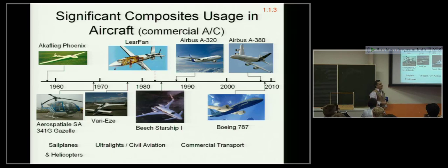In the 70s, he recognized that these composite materials would give certain advantages. They could give you pure laminar flow, because if you make the whole structure without any rivets, and you can maintain the aerodynamic shapes you want, which you can with composites with the use of proper molds, you can actually get laminar flow, and your drag goes way down. And he also recognized that you can generate shapes, such as canard shapes and so on, that will give you some extra performance in certain windows of the performance envelope.